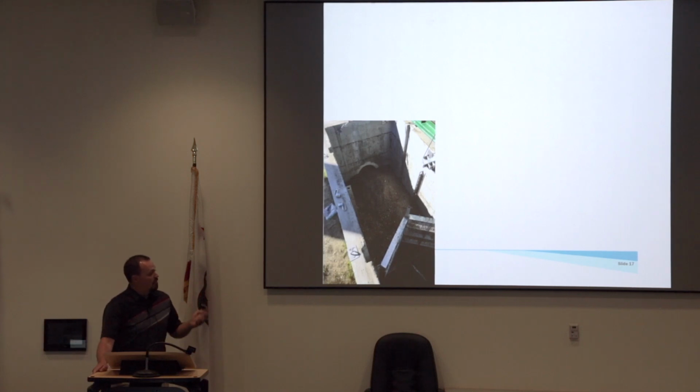We're trying to get all these kids to understand what they're doing when they're littering, things like that. But this is after the most recent rain event. At the start of January, after the Thomas Fire went through, we had this cleaned out, and this is what resulted after the one rain event. This vault has about, I think, 9 cubic feet of sediment storage, and it was completely taken up from that one event.